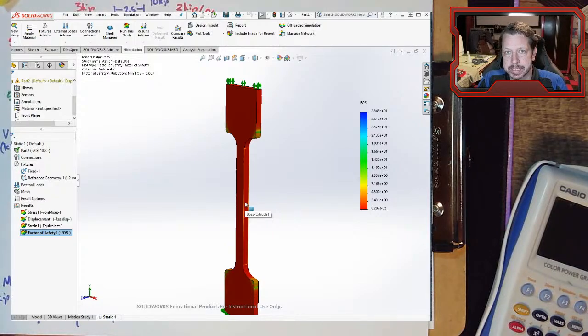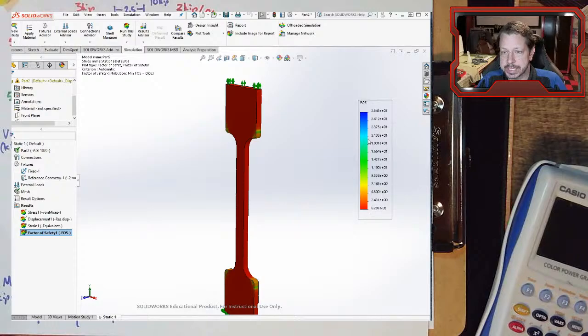But if you're doing a tensile test, then you actually are trying to pull it apart. So you do want it to stretch and then break. So we could get an idea of the stresses that are in it. If we wanted to, we know this area, right? This area was 1/4 inch by 1/8 of an inch, 0.25 by 0.125.